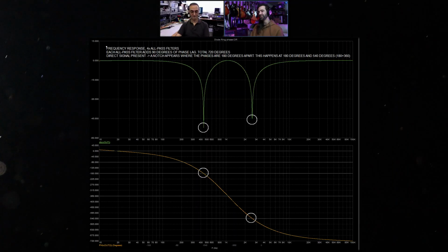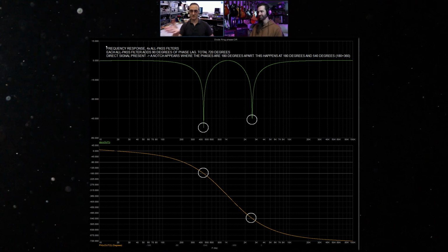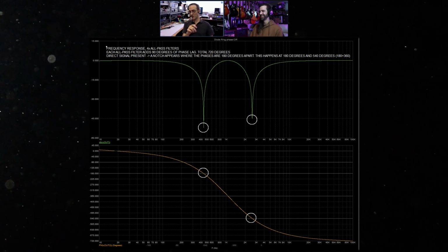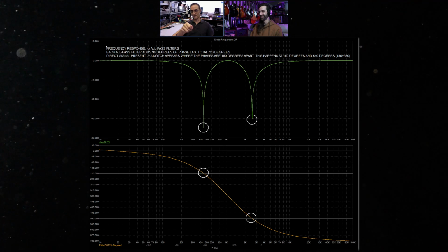With a flanger, the notches are going to be quite predictable, right? Because of the delay relationship. Whereas with a phaser, you can make the notches non-harmonically related. I mean, they're all predictable in the way that it's all mathematical. The phase shift is, but in the phaser, usually they have this control that Boss calls manual. That is the one that offsets which frequencies you want.